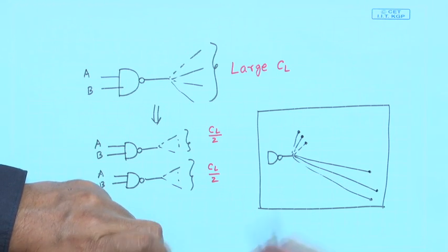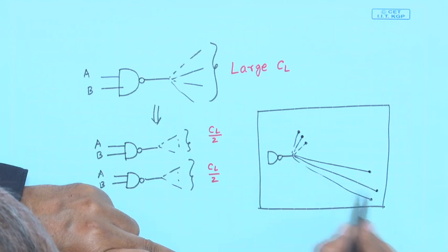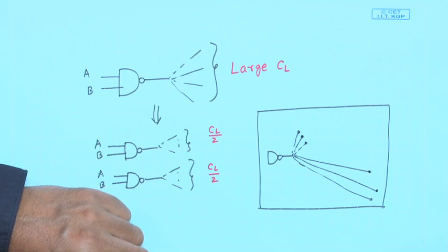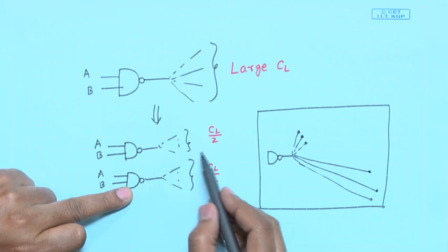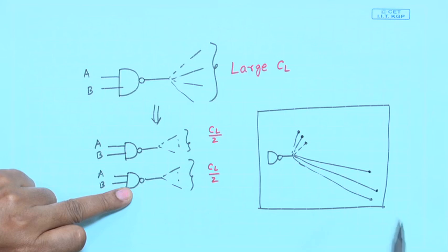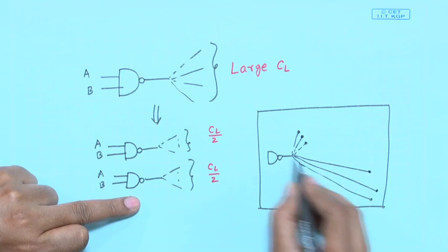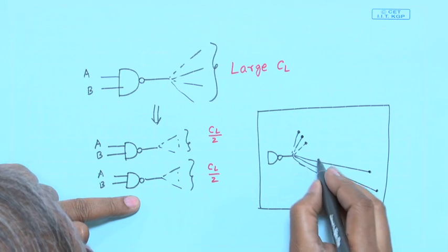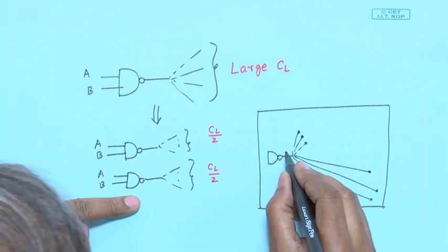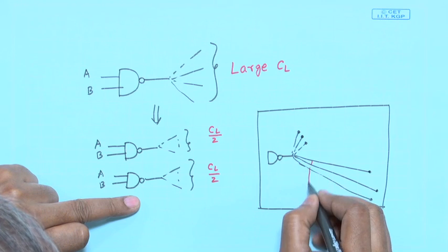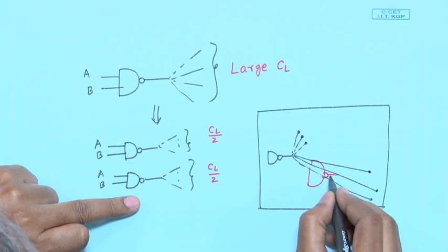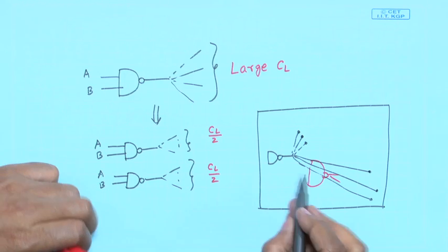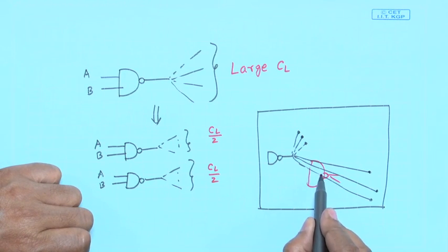Far apart means each of these long lines will contribute to a long interconnection delay. So, intuitively these gates can be inserted to handle these long interconnection lines. Maybe instead of driving directly this long line, you replicate it, and another copy you use to drive these, and this gate you can locate in a suitable position, not here, maybe you can place it here or here.